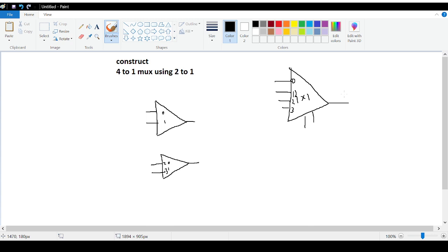1. So what we will do is, since we get 2 outputs here, one of these outputs will be shown as the overall output, so I will need another 2 to 1 mux here. Okay, so this will be 0 and 1, and this will give me the output. Okay, why do we do this? We will see later. Okay, because out of these two outputs, only one should be selected as my overall output, because my overall output should be 1, and this mux has 1 selector bit.